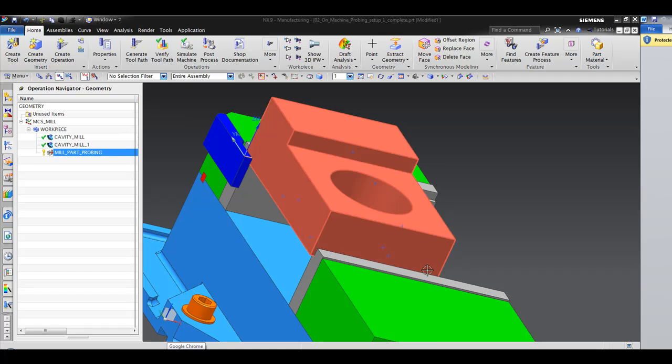I've created 2 points, so I'm going to show you how to record that information on the controller in a structured manner. You can have variable 101, which is the first point, 102 the second point, 103 the third point, however you want to do it.